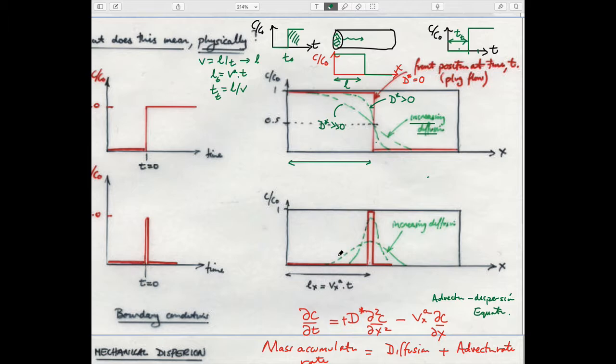And so you could imagine if you took the concentration of that as you go downstream, it would have a large concentration. If it didn't diffuse, as it was pushed downstream as the wind blew, it would just move down as a skyscraper and be carried down as that tower. If it diffuses and tries to get rid of this infinite concentration gradient by physically moving to each side, then progressively, as it goes downstream, it will look like a hill that gets lower and lower.